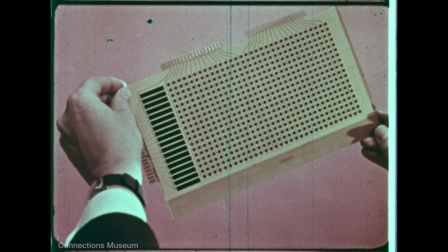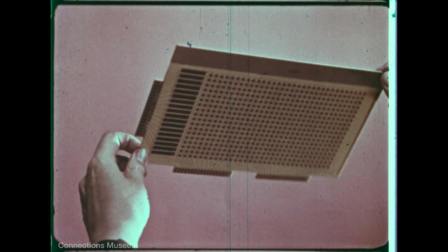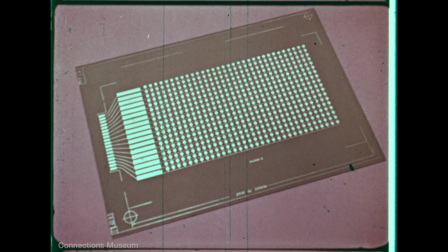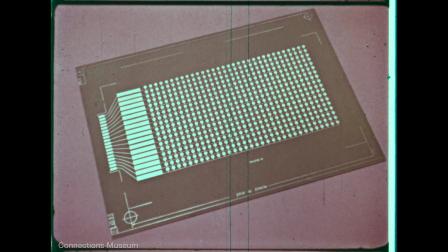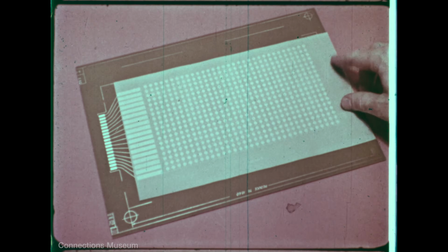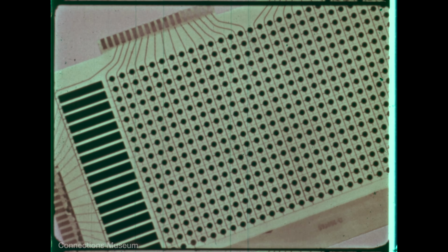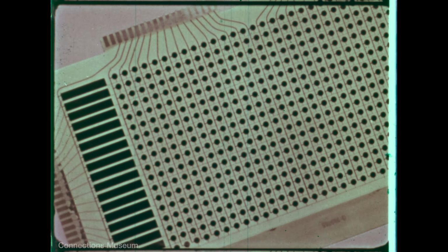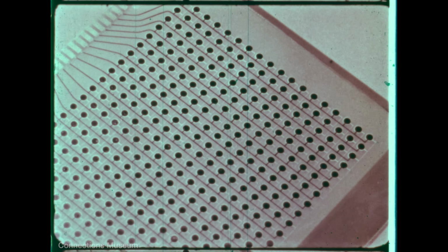Another simple permanent memory device stores bits by the presence or absence of small capacitors in a grid-like array. On a plastic sheet, rows of copper spots connected horizontally by electrodes are printed by an etching process. Then a thin sheet of non-conductors such as mylar is placed over the array, and another array of copper spots connected vertically by electrodes is matched over the first, forming a grid of small capacitors connected by coordinate electrodes.